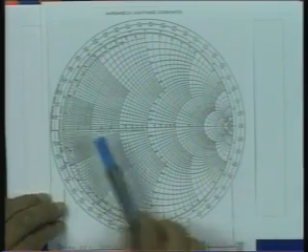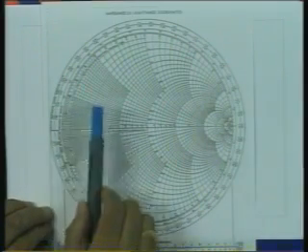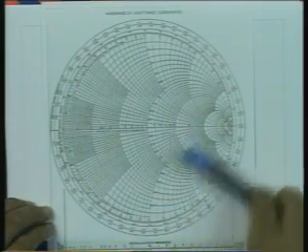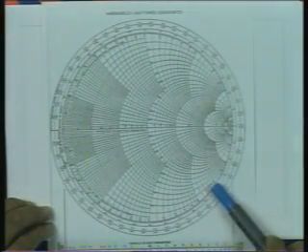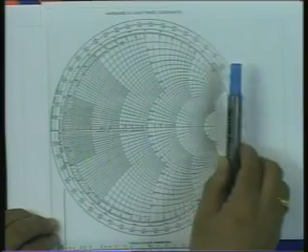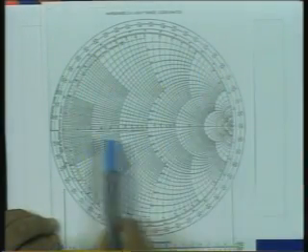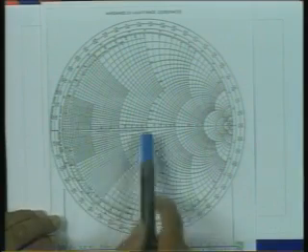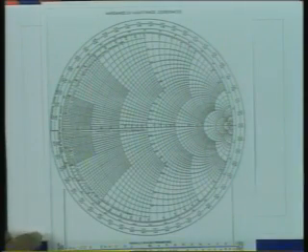So, now if I want to plot or mark an impedance point on the complex gamma plane, these are the coordinate systems which I have now, and this is an orthogonal coordinate system. You can take the corresponding values of r and x and find the intersection of the two circles corresponding to that constant value r and constant value x, and the intersection point will represent the impedance for that value of r and x.